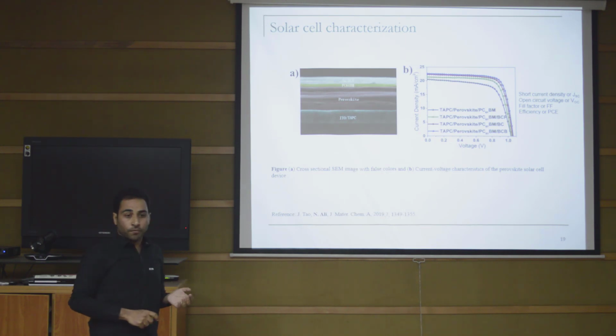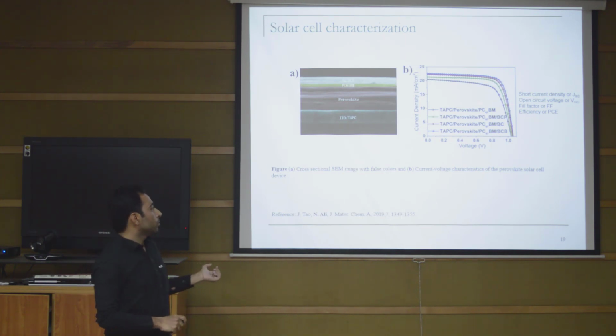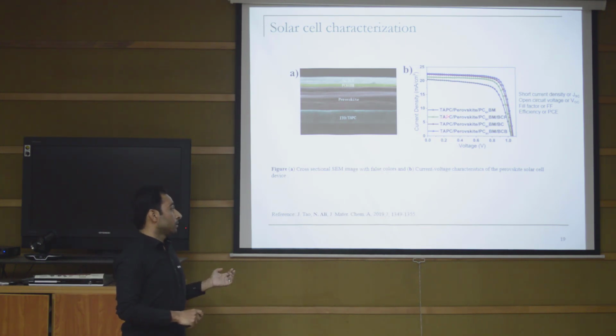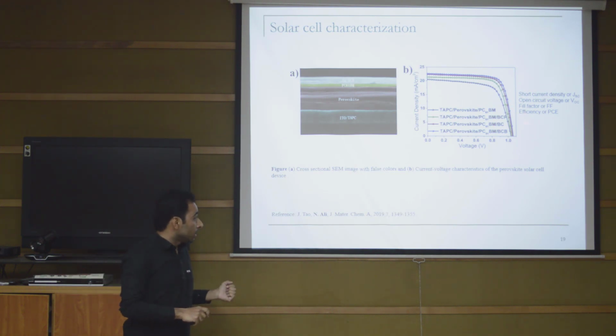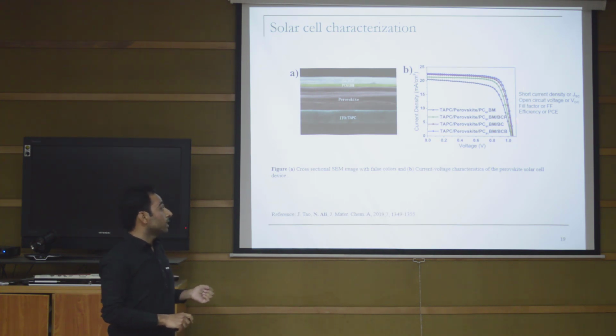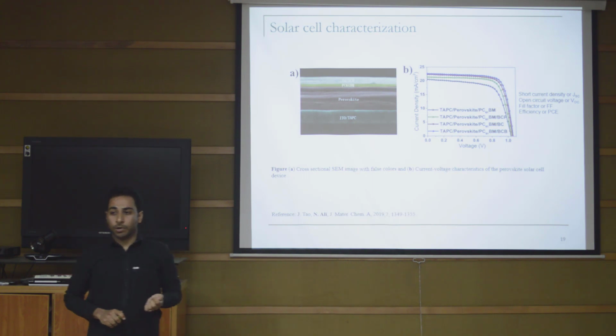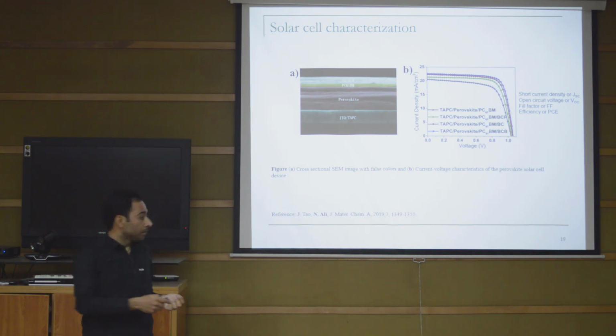density and voltage profile. For this you have to use the solar cell simulator, and this simulator will directly calculate all these properties. Otherwise you can also calculate these characteristics from this graph, like the fill factor, open circuit voltage, short circuit current density, and the most important, the power conversion efficiency of the cell.